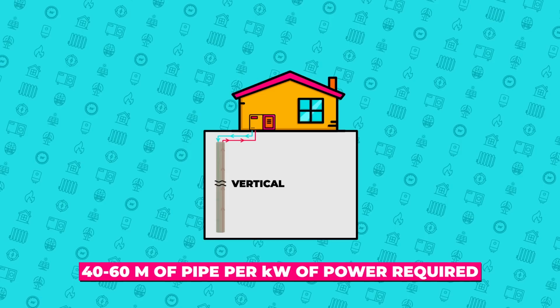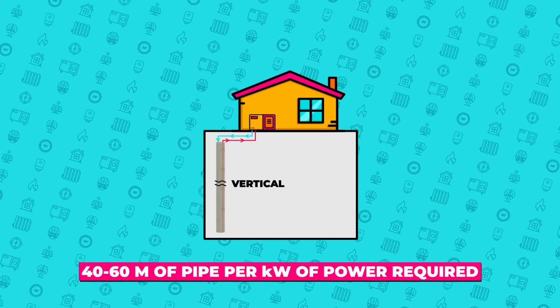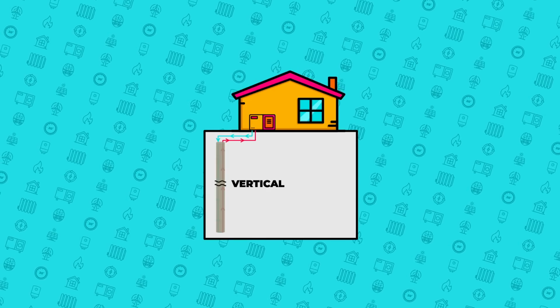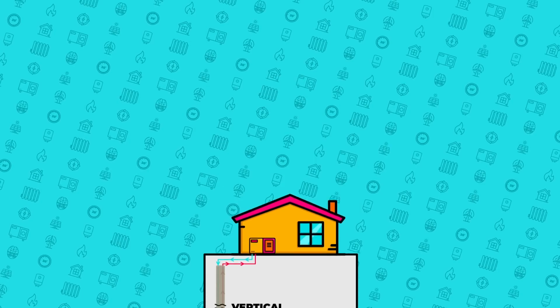The installation will need approximately 40 to 60 meters of pipe per kilowatt load required, but needs a full calculation. Several boreholes will be needed for a typical house, the number of which really though depends on how deep they are, and a full geological ground survey again is essential.